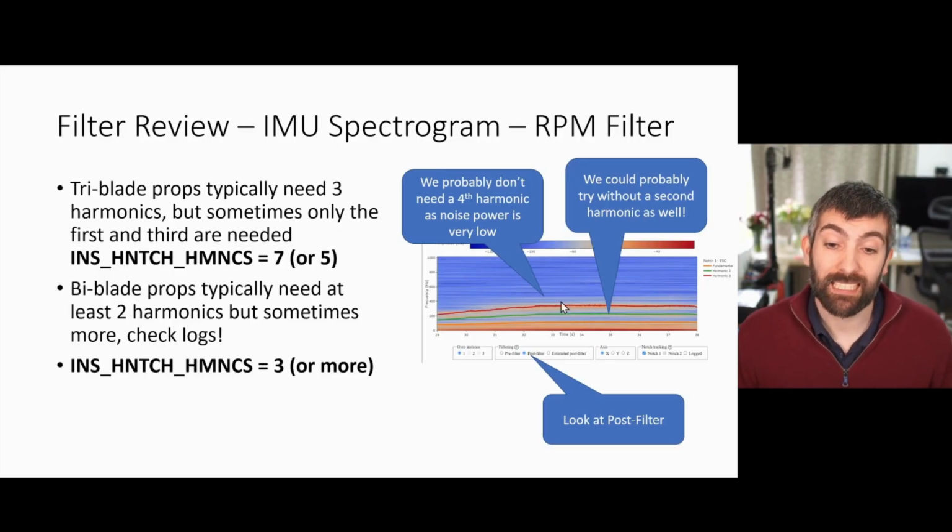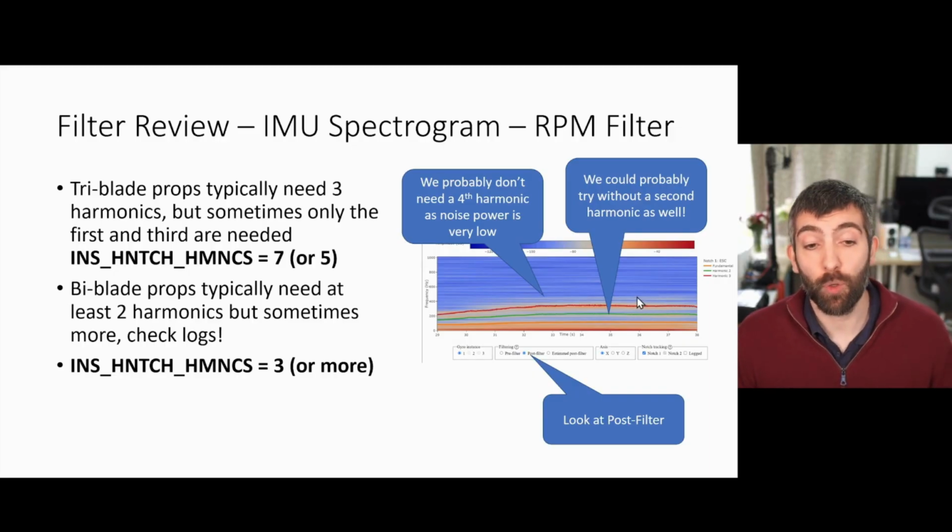And in my case, that makes this fourth harmonic completely disappear, because that fourth harmonic is at such a high frequency, nearly 500 hertz, that the gyro low pass filter does a fantastic job of just crushing all that noise away, and so we don't need a notch there.